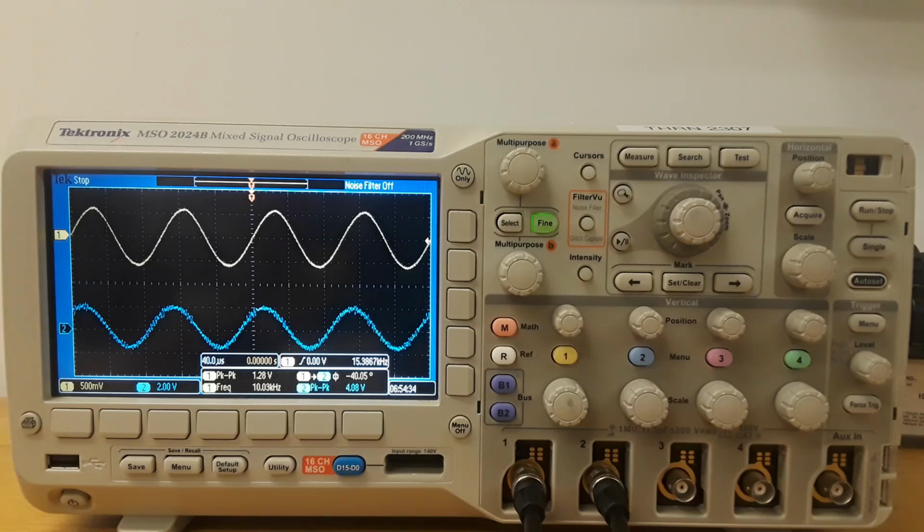Another thing that we see on this is the phase shift between the two signals. So this one, channel 1 here, is the input. It's being read by the processor. But the processor needs to take some time to actually do the processing on it. There's not much processing, but there is still a delay between those two signals. And you can see that delay on this output works out to a phase shift of what the oscilloscope reads as negative 40.05 degrees. But in reality, because the output has to come after the input, it's going backwards about a delay of 320 degrees.